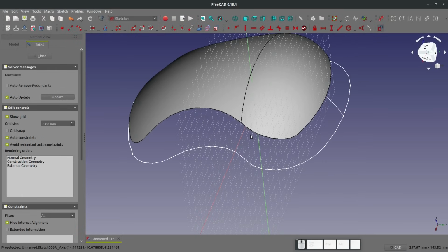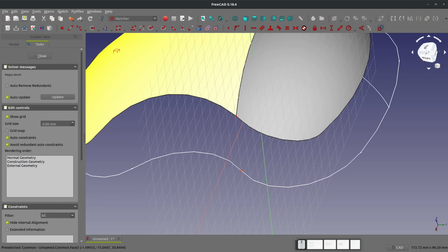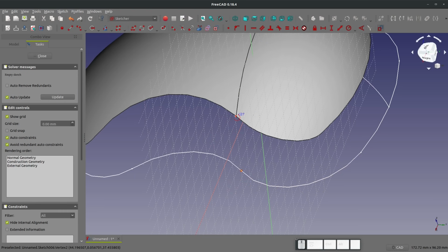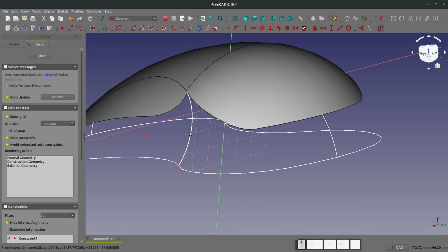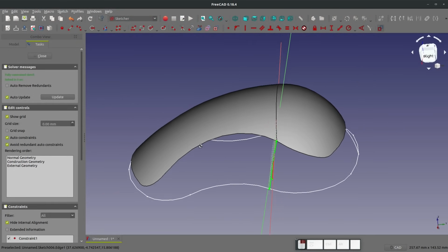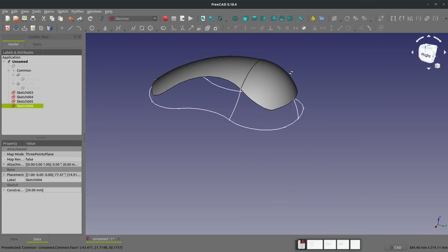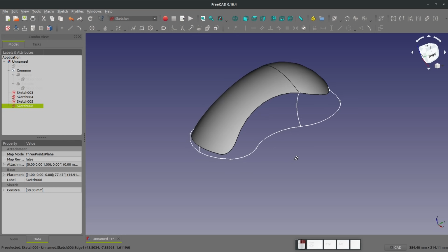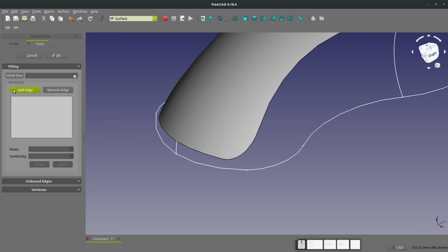Now I want to use my import tool, and I'll import 2 of the points that I've just created, there and there, and I can make a 3-point arc. Right, look how nice that is. So we're going to say Shift R to give that a radius. 30 millimeters is fine. Now I've got this little radius that dictates some curvature, and there's a few things I can do with that. I'll again fast forward so you don't have to sit through me monotonously clicking points, but we'll go to the surface and choose my filled surface here.